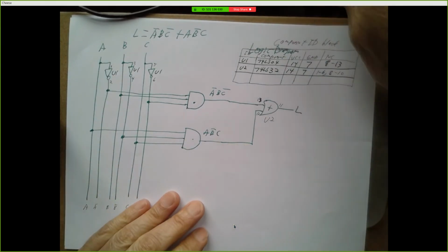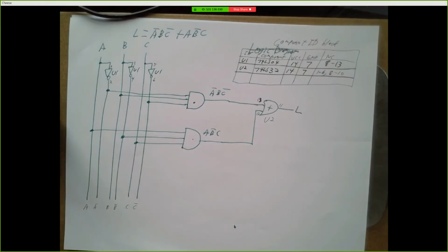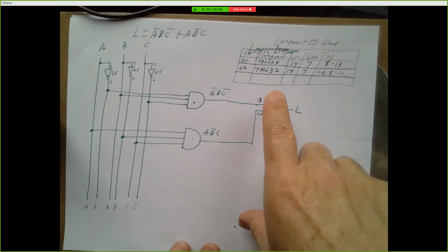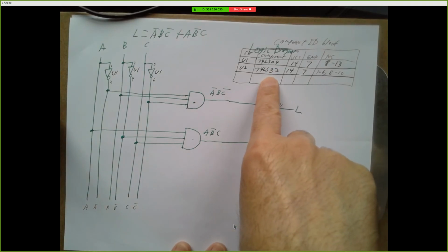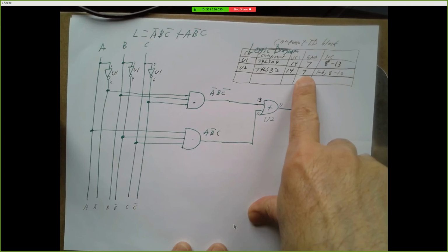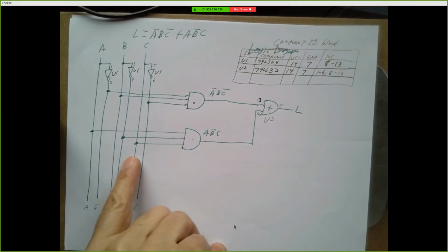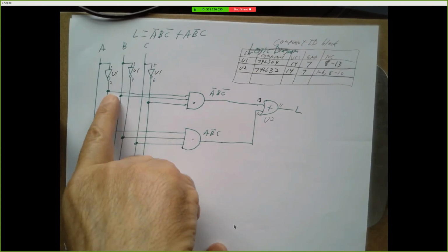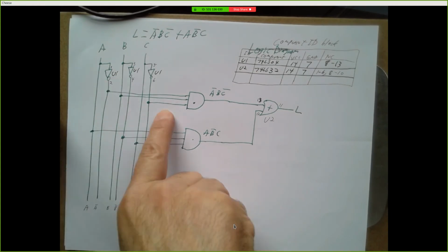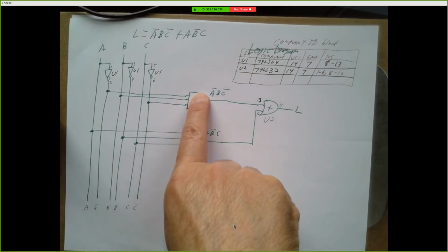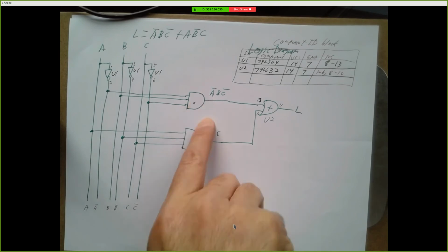And when you're done, you have a complete wiring diagram. Okay? It's a diagram that means you never have to look at your data sheets again. You basically pull these components out from your parts bin, you plug them into your proto board, you connect ground to here, power to there, and then you just start running wires. I need a wire from pin 2 on chip U1 to pin whatever this is on chip whatever that is, right? Probably U3.